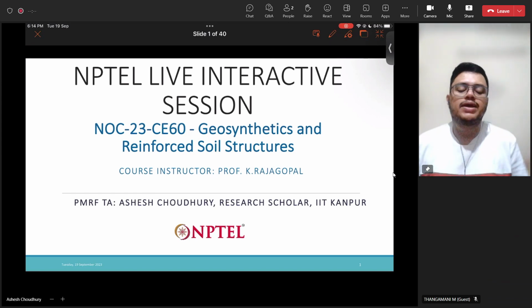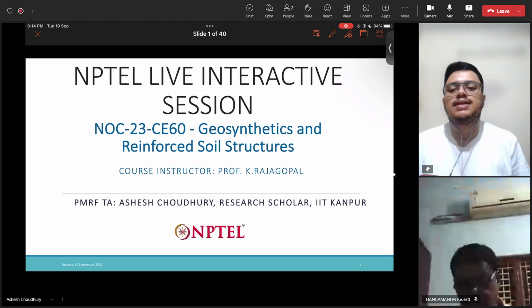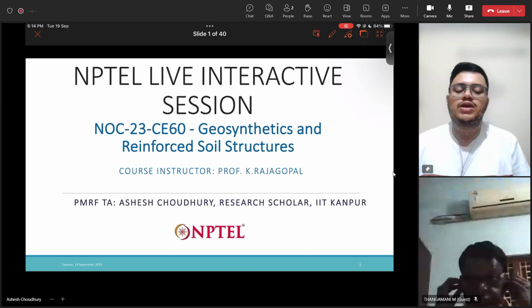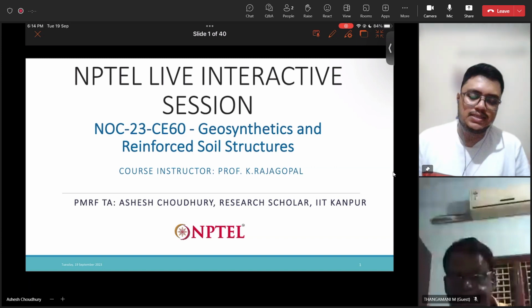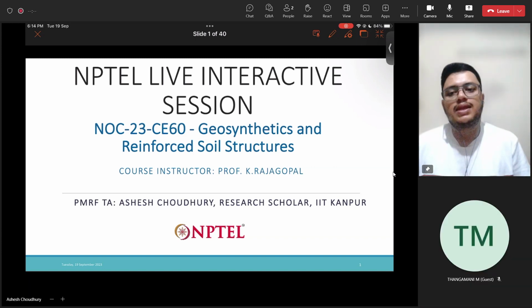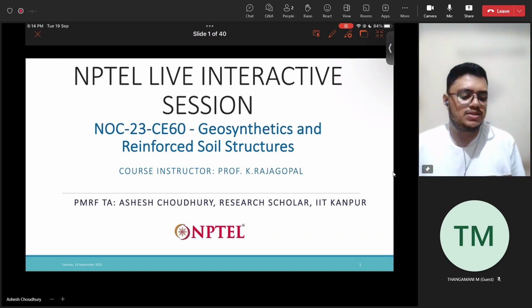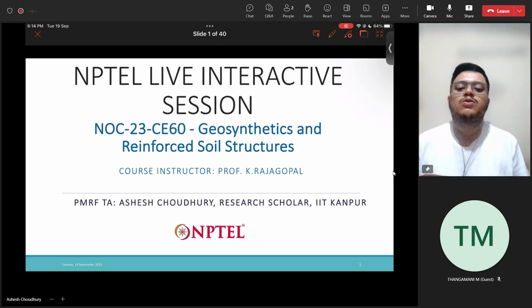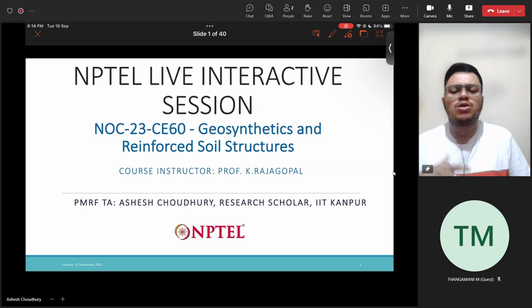So today we will recap whatever was taught in the previous session, that is, the use of reinforcement: geotextile, ties, or any other steel strip, any reinforcement to improve the bearing capacity of the soil, how that is done, and the theory behind it. Then we will solve the problem that was discussed in the class, and see if we decide to use a different width of strip footing, how everything changes.